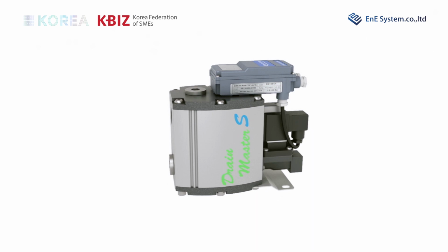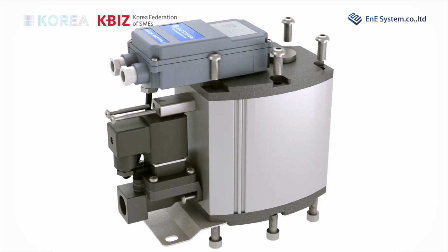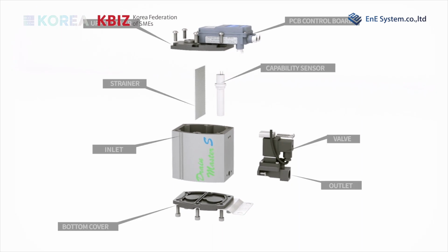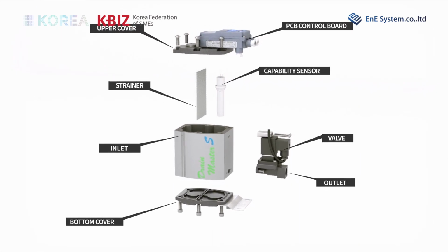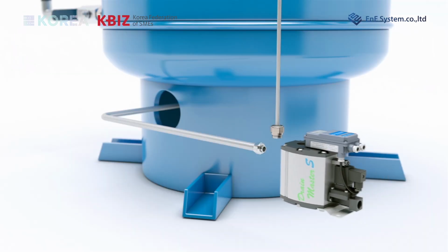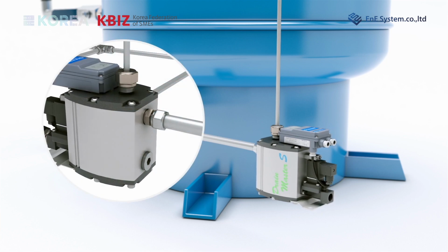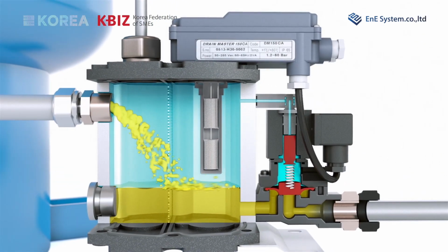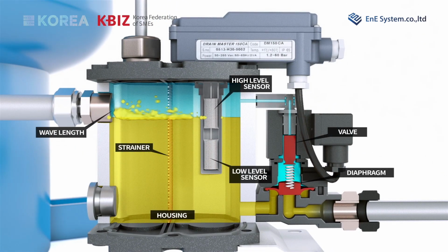As to the principle of Drain Master's mechanical performance, condensate accumulated in the housing is detected by a level sensor, which triggers operation of a valve, and this allows compressed air in the upper part of the diaphragm to be vented, creating a state of atmospheric pressure. Then, condensate is discharged through the drain line by the pressure of the diaphragm of the valve.